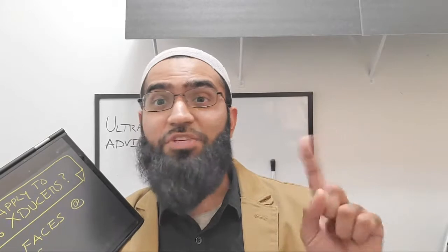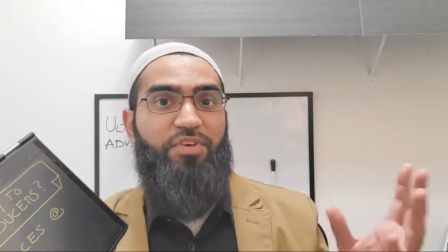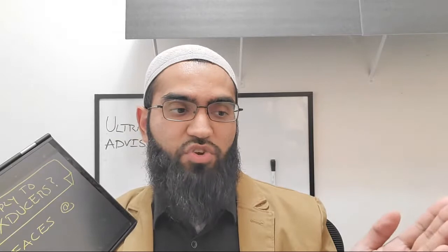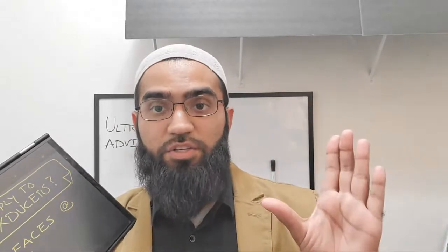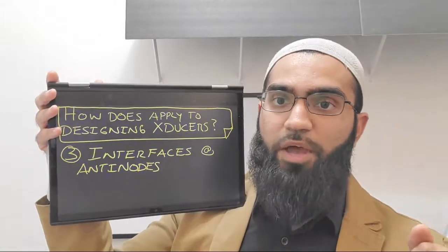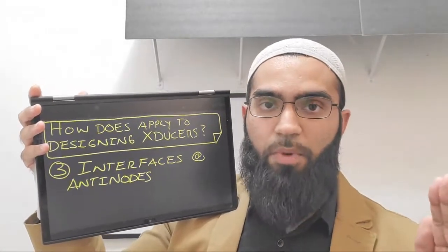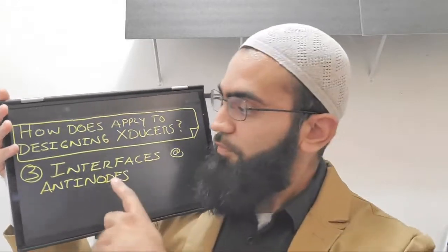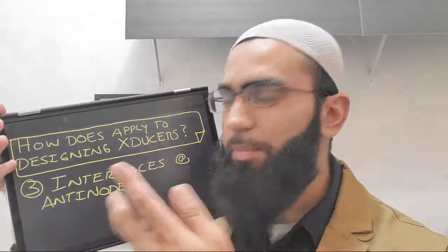In FEA, this won't matter at all because you have perfect bonding between components. This is one of the differences between FEA and reality, whereas it won't matter as much to have an antinode at your interfaces in FEA, in real life, you're going to experience that difference immediately. So that's one thing to keep in mind, a rule of thumb that you get from experiments that you won't get from an FEA simulation, or the effects of it won't show up.